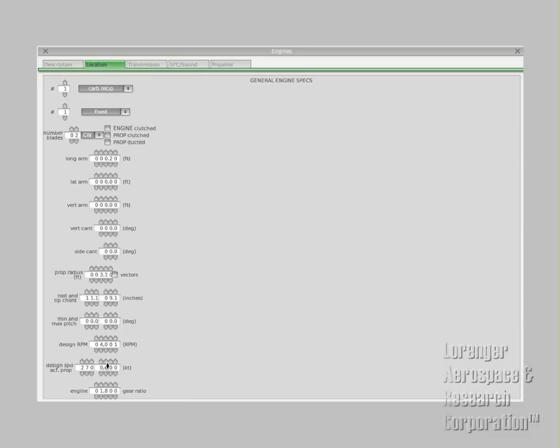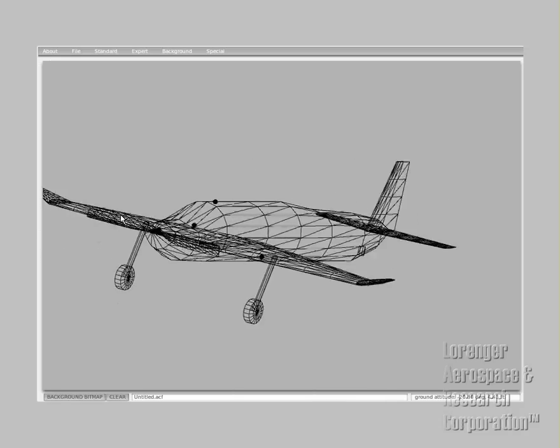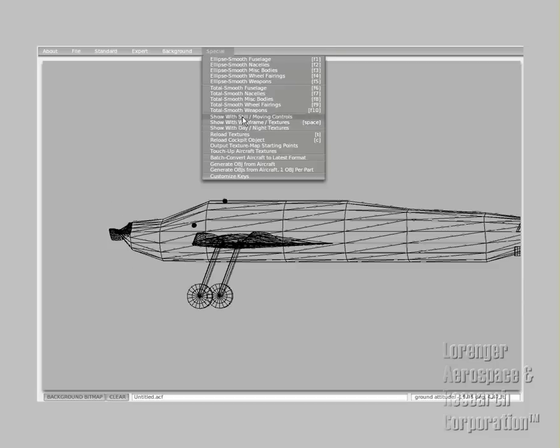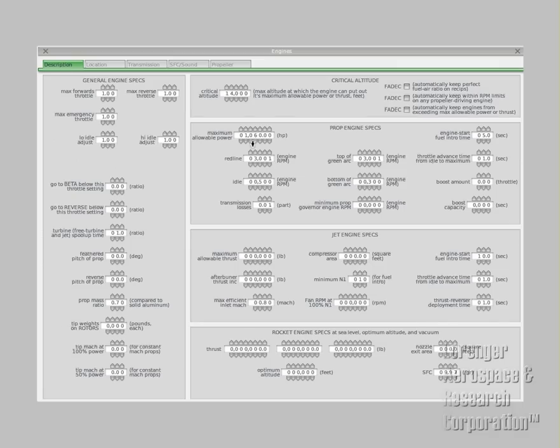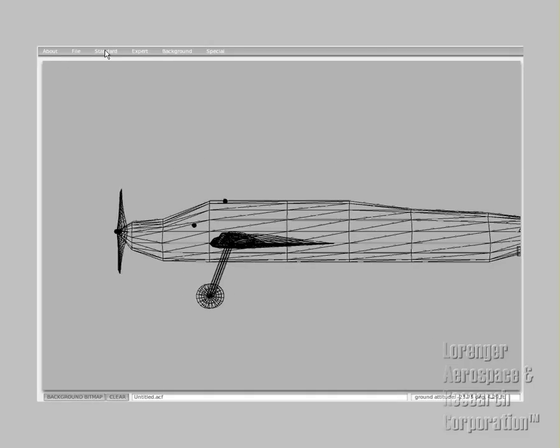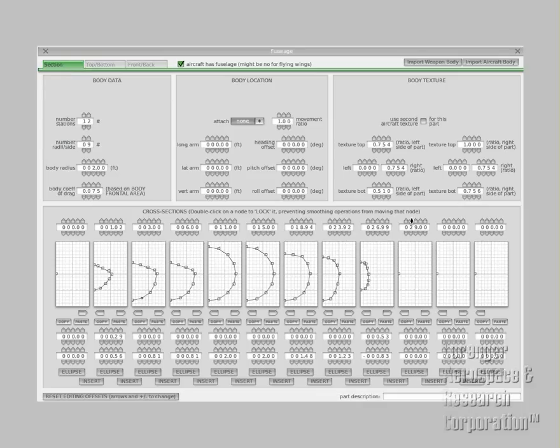Oh, wow, that propeller is terrible, so we're going to thicken it up a bit. And here I forgot, it's been a while since I used PlaneMaker, so we're rolling around, realizing it's a little too short, make it a little longer, whatever. Now we're going to rotate by using animate free surfaces, and it shows you what the bits and bobs will do. Also, if you notice, the control geometry isn't moving yet. We have to set that. We have to set the depth of the ailerons, rudders, and elevons to a certain chord percentage, and also the deflection angles. More on that later.